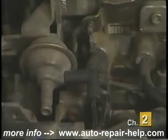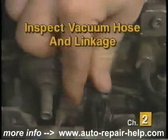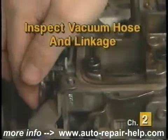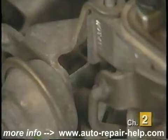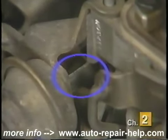If you suspect your choke pull-off is not working, the first step is to perform a visual inspection to make sure the vacuum hose is connected and in good condition, and to be sure the linkage between the pull-off and the choke blade are actually connected. If both areas appear all right, then start the engine and watch for movement of the pull-off. No movement indicates a defective pull-off.